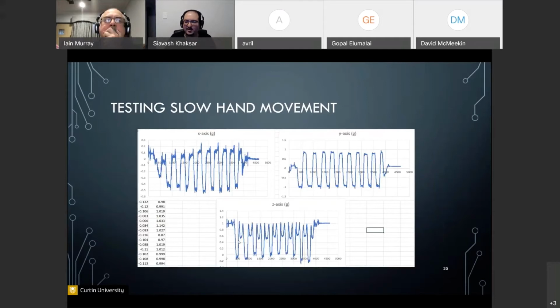And here you can already see the problems you can have with IMUs in terms of drifting, especially on the z-axis. You can see it's drifted so much down, so it definitely needs to be filtered, so the data can be actually used without having to worry about the abnormalities that we can see in there.